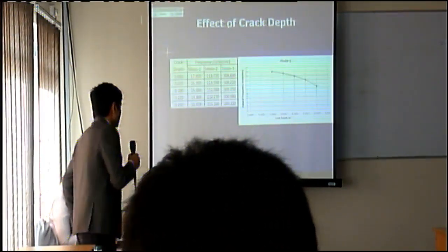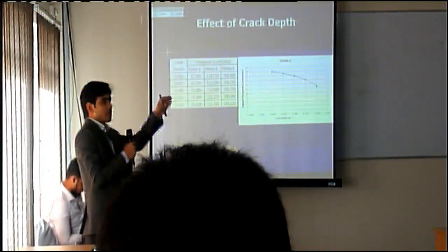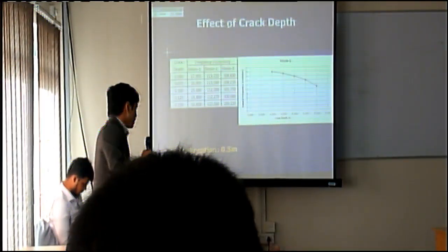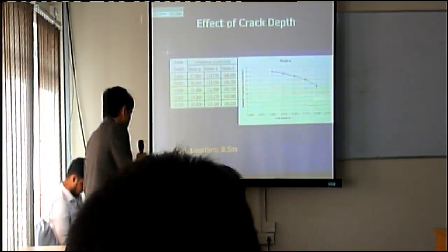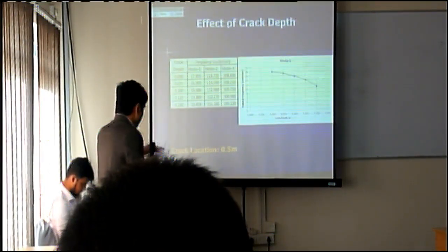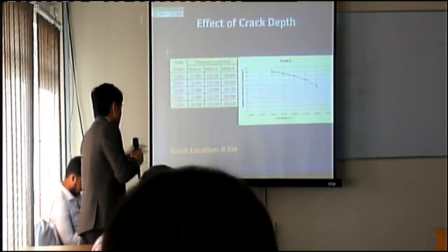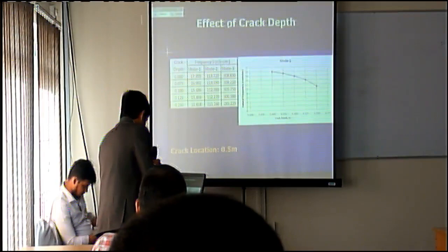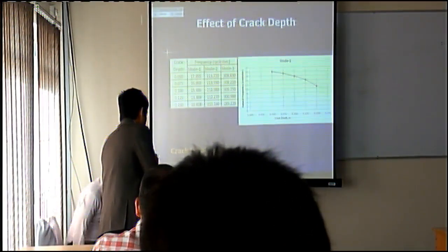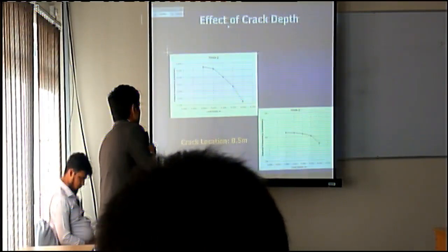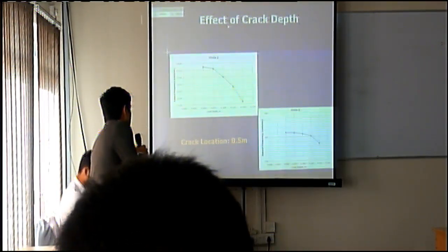Now the effect of crack depth. As the crack depth increases, the frequency reduces more. It is because of the bending moment, the stress. The stress is higher as the crack depth increases and the frequency reduces. These are the results for crack location 0.5 meter for different crack depth. The similar pattern is found for mode 2 and mode 3.